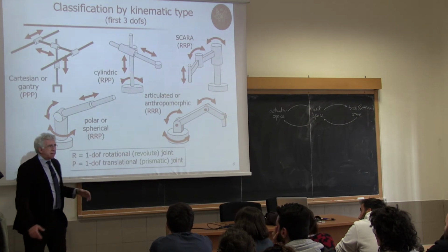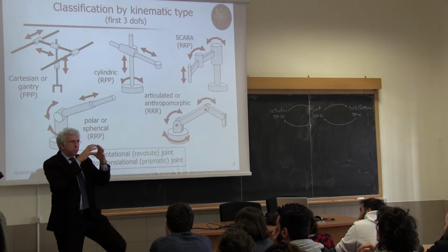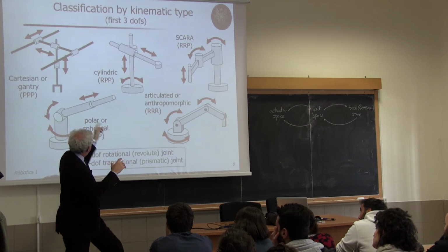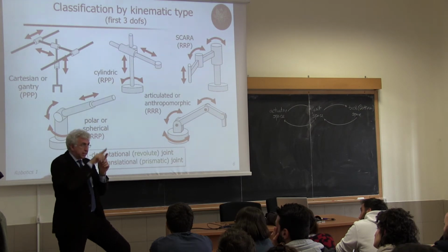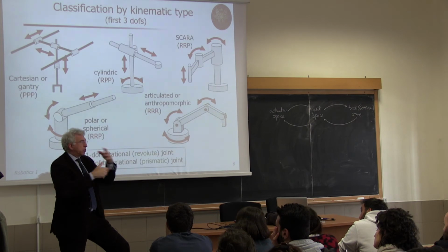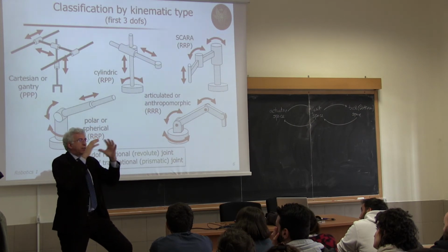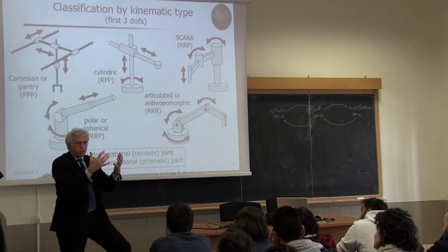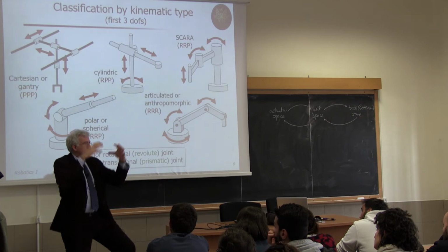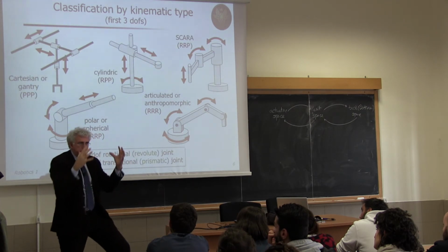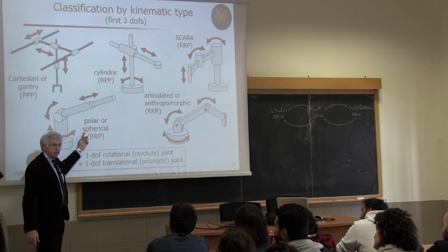It's also called spherical because if you freeze the last joint, the prismatic joint, to a value, and use the other 2, the end effector of this robot moves on the surface of a sphere, and now if you move the 3rd joint, this sphere is growing or reducing. This is why the terminology is spherical.